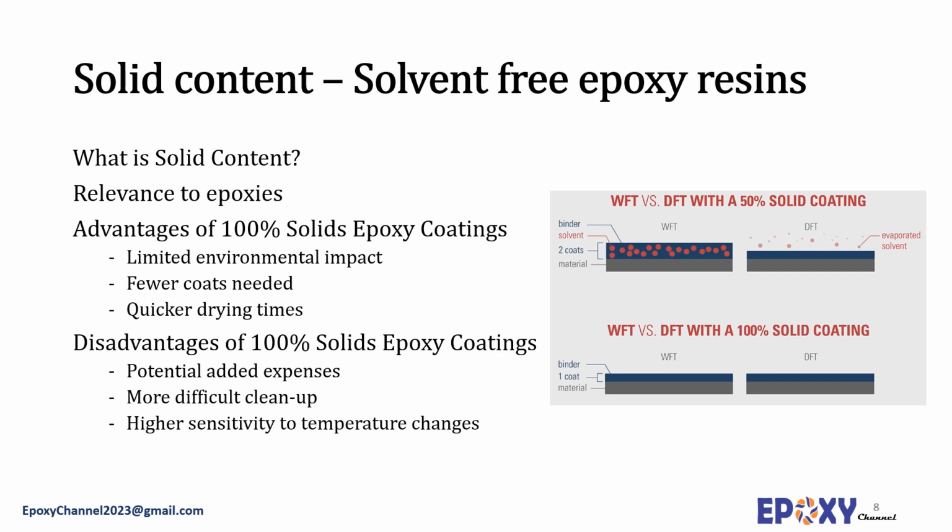In 100% solid, fewer coats are needed. The DFT of low VOC epoxy is the same as or close to these coatings' WFT. It means that you need fewer coats to get the same results you would from a high VOC coating. Also a big time saver for your project because the solvent has to be evaporated eventually.